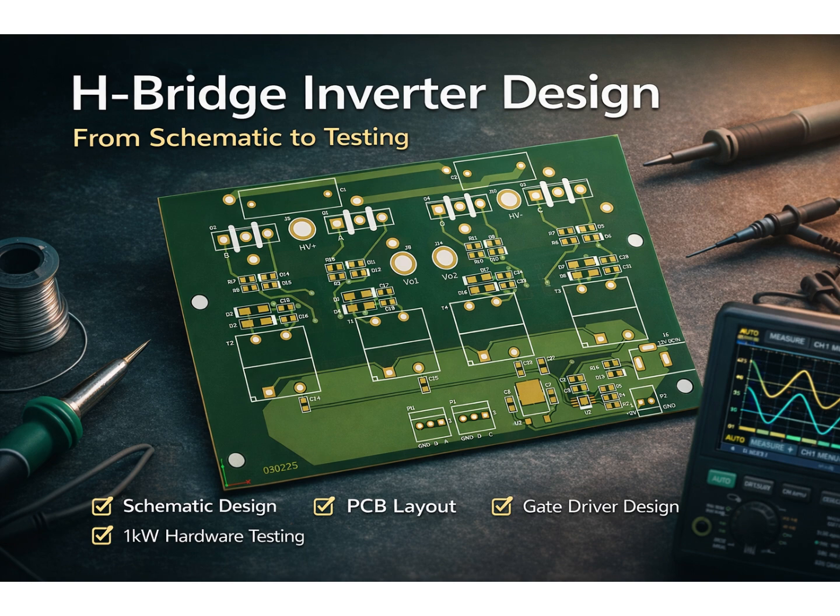We will also design the isolated power supplies required for gate driving and explain the working of isolated gate driver ICs in detail, why isolation is required, how it improves safety, and how it prevents control side noise. On the control side, we will generate PWM signals using an STM32 microcontroller and discuss timing, dead time insertion, and safe switching practices. Finally, we will move to real hardware testing, connecting the inverter to a 1 kW load, capturing voltage and current waveforms on a digital storage oscilloscope, and analyzing switching behavior, output quality, and performance.